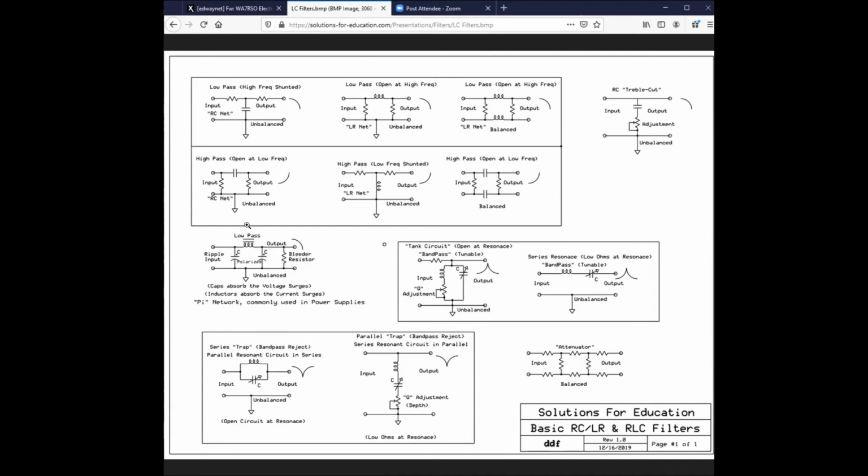This one here is typical for a power supply. A power supply normally has a capacitor here, and the inductor there. And by the way, if you build this circuit in the lab, you'll find that this capacitor here affects the overall output a surprising amount compared to this one. Well, that's because of the way it's following this inductor. Anyhow, this is a typical one.